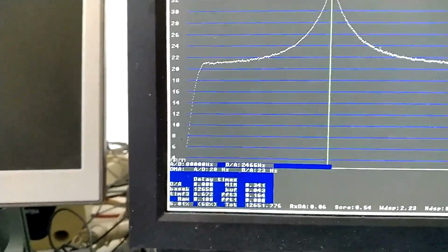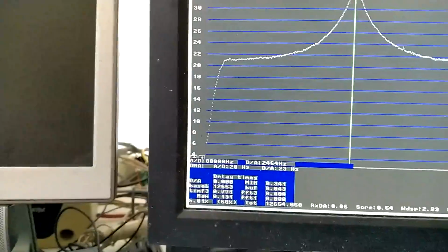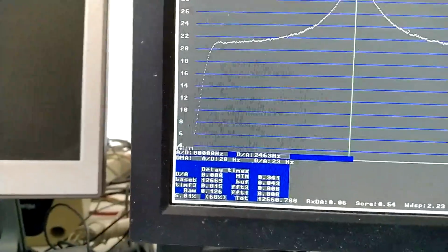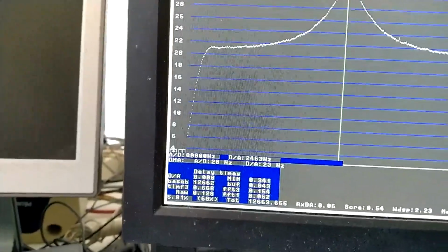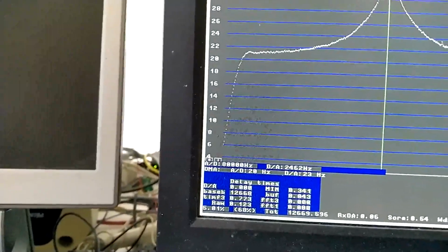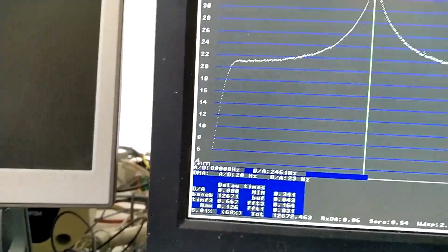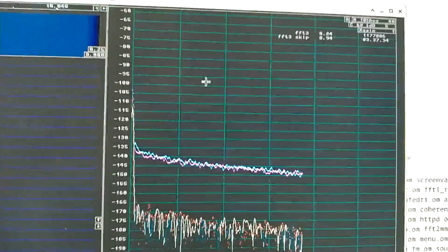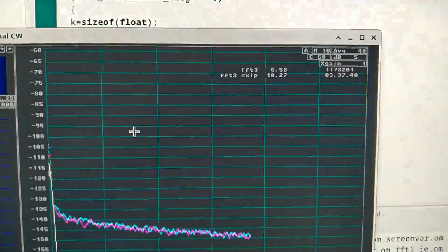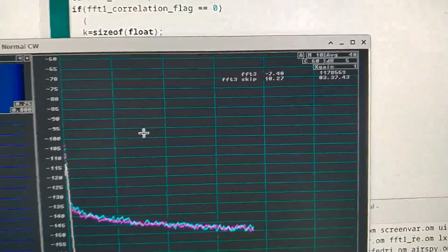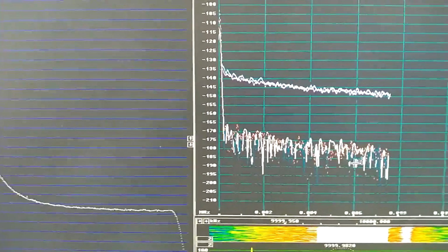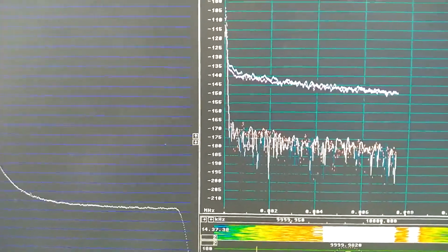This does not work properly either. You can see that the total delay here is 12,000 seconds. So data is accumulating in the buffers and things will fail fairly soon, I think. And the data is piling up in the baseband buffer. So it means that this procedure doesn't swallow data fast enough, even though I changed the transform size from 9 to 10.